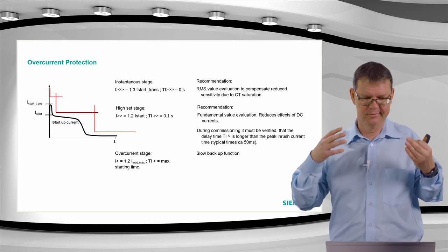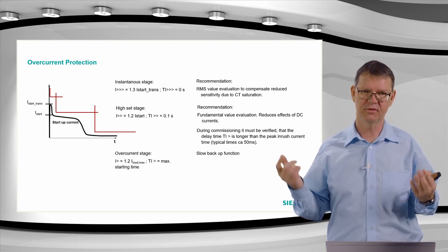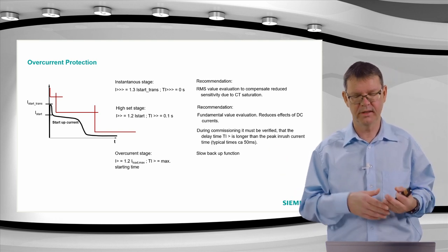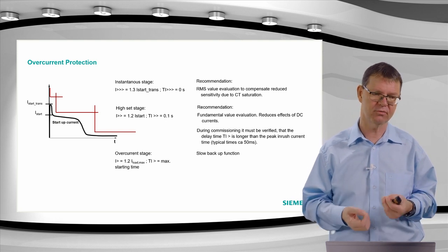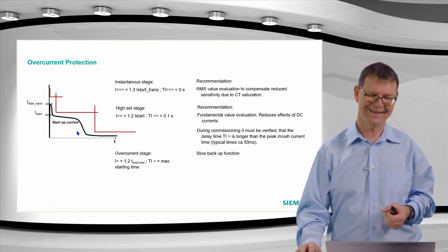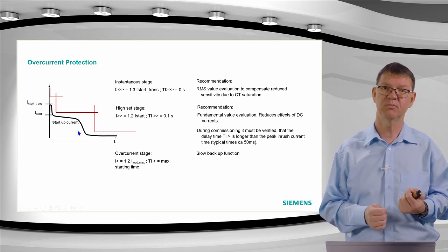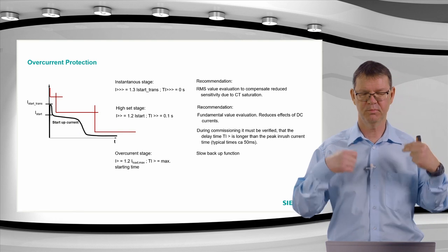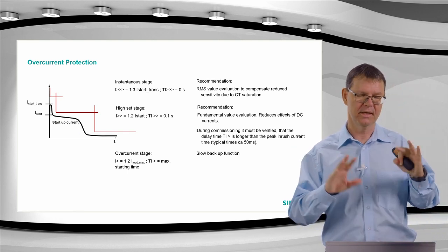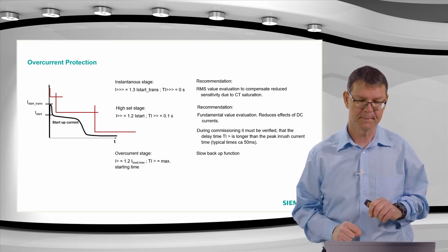We can apply just ground overcurrent stage 50/51N. The setting here depends on what we encounter as a measurement error during the startup. So I would say have a look at the apparent ground current which you see in the relay when you start up the motor, and then put a threshold here with a big margin on top of that, so 10-20% maybe. And then you have a relatively sensitive single phase fault protection additionally.